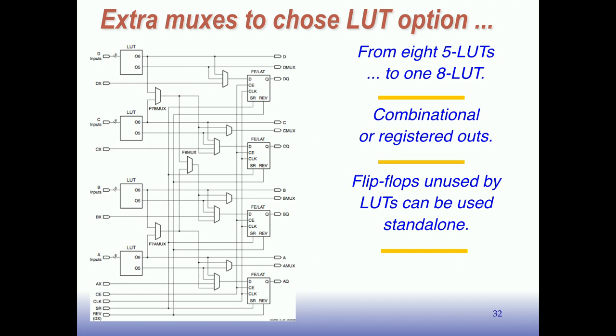There's an interesting thing about FPGAs. Designers figured out you can add this kind of functionality without affecting the area of the chip very much. The CLBs are relatively large already, and a lot of the area is in the wiring. So by adding a little extra logic into the logic itself, it makes it more flexible and more useful for the user, so there's been a tendency to add that extra functionality. It comes at an incremental cost, but it may be just the right thing for somebody's circuit to run faster. So you see a kind of feature creep in FPGAs over the years. They've gotten more and more complicated as more and more features have been added.